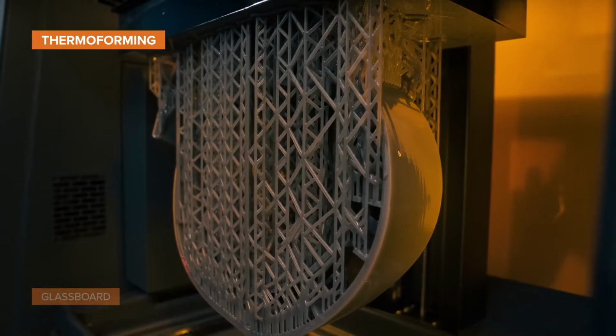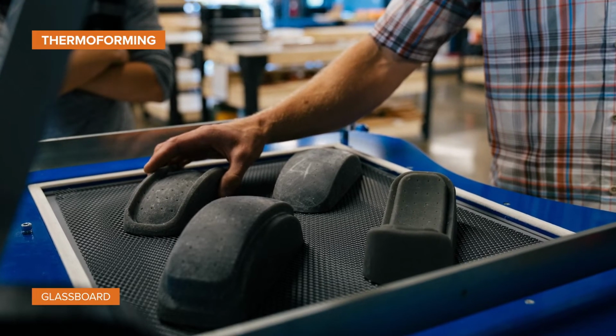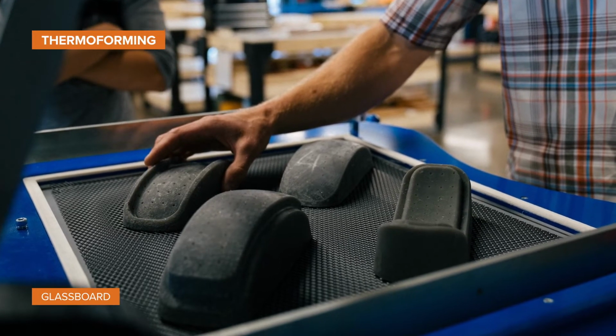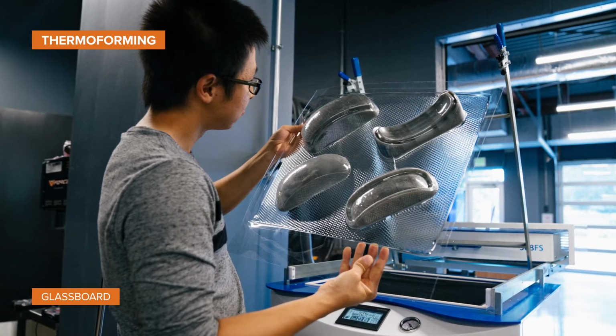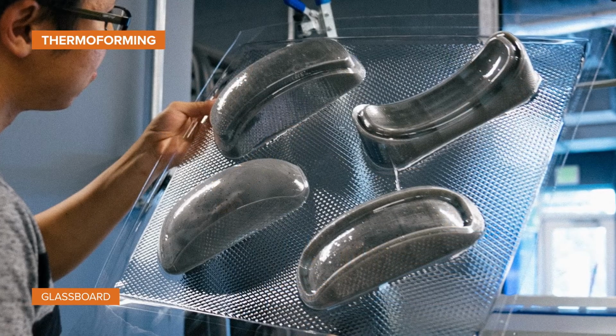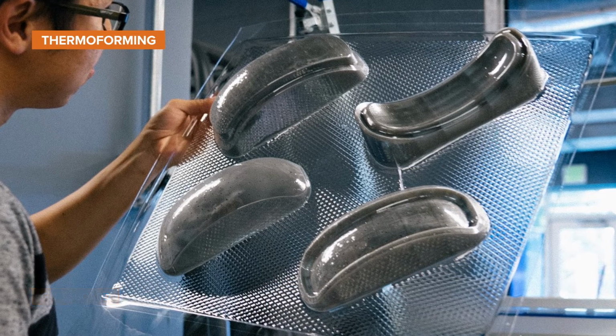Product development firm Glassboard leverages the printing speed of Draft Resin to quickly produce molds and thermoform polycarbonate prototypes such as helmet shells or packaging. They can achieve complicated mold shapes that would be difficult to manufacture traditionally, including small features and holes for an even better vacuum distribution across the surface.